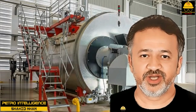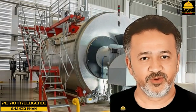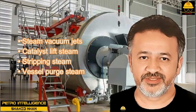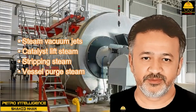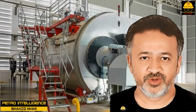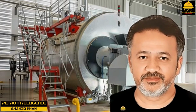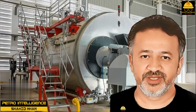Contaminated condensate reuse. Much of the steam consumed in process units comes into direct contact with the process streams. A few examples are steam vacuum jets, catalyst lift steam, stripping steam, vessel purge steam. For corrosion and safety reasons, the condensate recovered from these sources is best not returned to the deaerator for use as boiler feedwater. However, there are no unchangeable rules in the process industry.